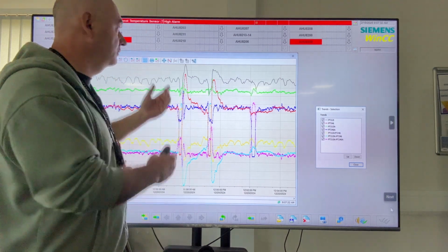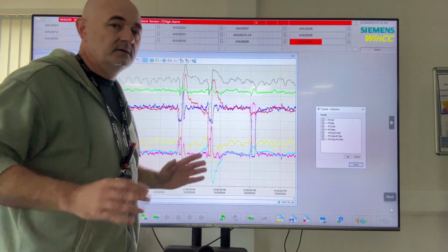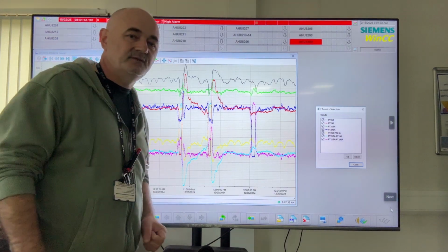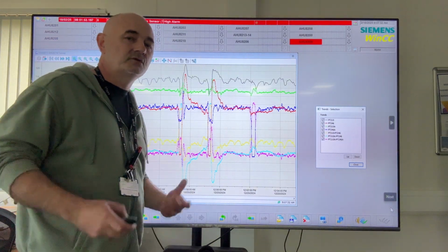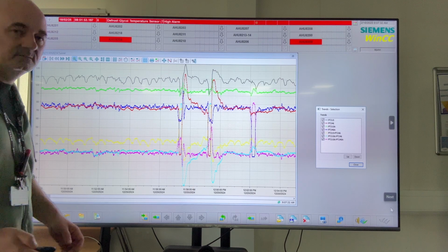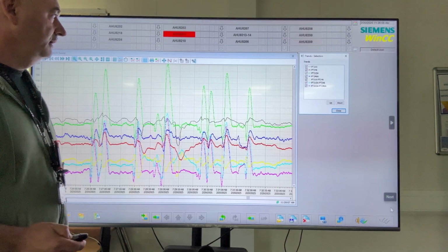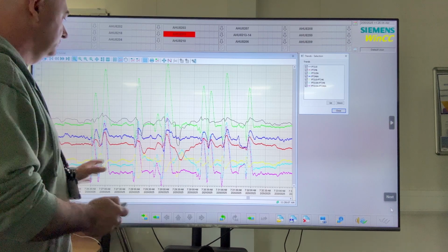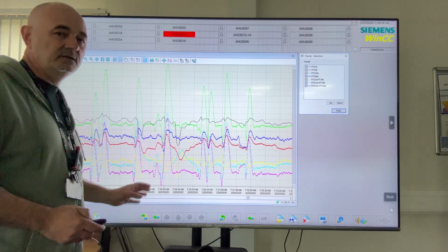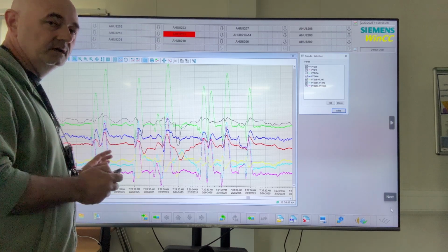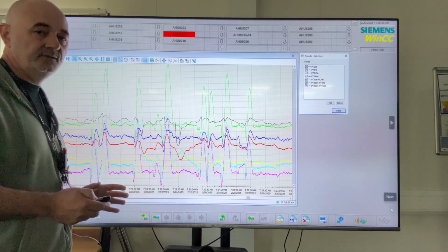Why did the pressure go so high on P215? In 99% of the cases in the past 10 years, P246 has been investigated, and AHU 813, which was a very incorrect approach, extremely incorrect. It has nothing to do with reality. I have more trends here to show you the amount of trends I have to read when I have a fault, to identify the real problem, not to work with effects, but go straight to the